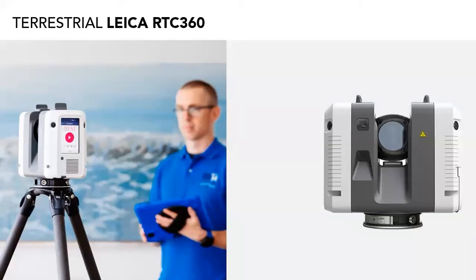Even though this needs to be set up on a tripod, the individual scan times for the RTC 360 are relatively short compared to other terrestrial scanners, making it the fastest terrestrial option out there. The iPad app also helps make sure that you can check your point clouds before leaving the job site. And even though the RTC is extremely precise, there are other terrestrial scanners out there that offer even higher levels of precision in their resulting point clouds.